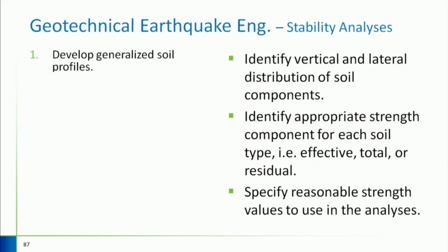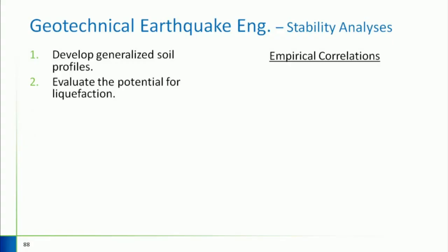Selecting reasonable strength is also another very difficult, tricky geotechnical aspect, but also a very important part of that generalized soil profile, especially when you're looking at earthquakes. There's a lot more parameters that we have to define than a typical slope stability. So once we have the profile, you've got to determine if it will liquefy, and if not, how do we have to mitigate this liquefaction, because that's going to contribute to the strength of these soil layers that you select when you run your model.